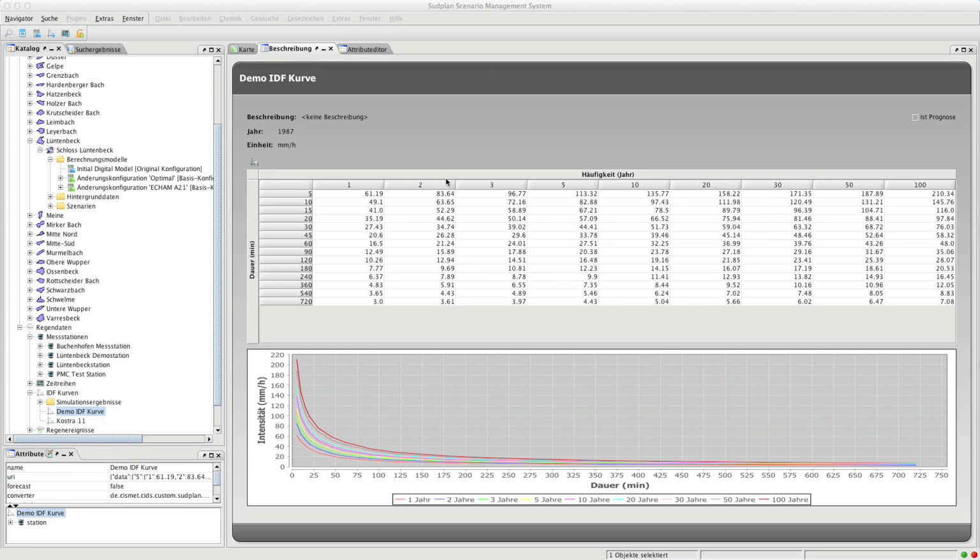We are nearly ready to do an initial runoff simulation. However, the runoff model cannot deal with IDF data, but with single rain events. Fortunately, the SMS supports generation of Euler rain events from IDF data. We simply have to select the desired range for the rain event and use the Euler rain event generator wizard that is available from the contextual menu of our selection.